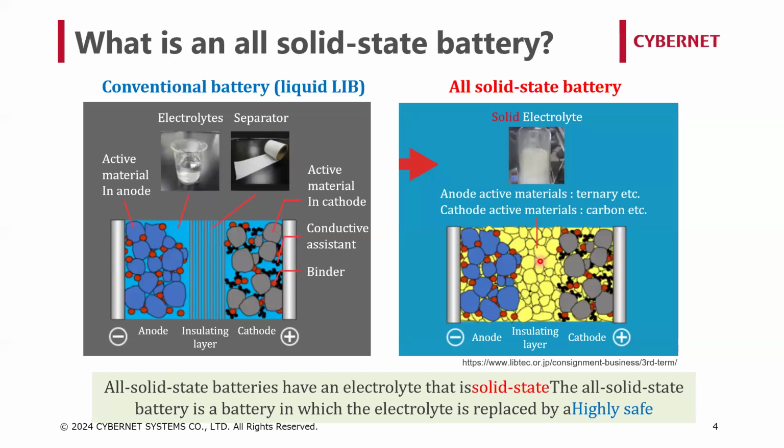So, as shown in the figure here, solid materials are crushed into pieces, in other words, powders, to obtain high fluidity. And it is filled inside the battery, and finally the products are made by pressing them. In order to improve battery performance, it is important to create a layer of solid electrolyte with a high volume rate and no voids so that ions can move well. And to have dense contact between the individual particles, controlling them is almost entirely a matter of the manufacturing process.